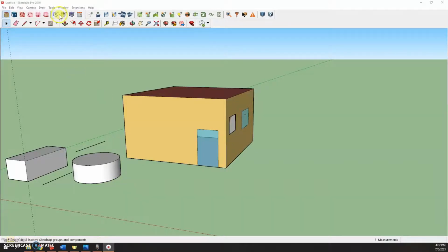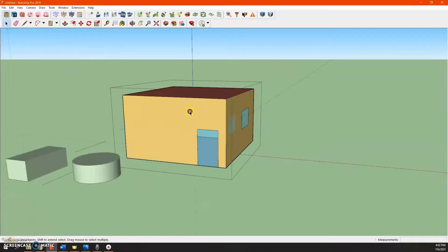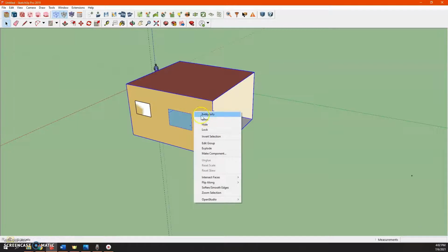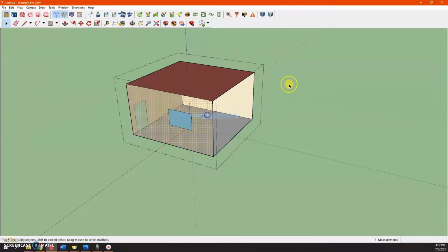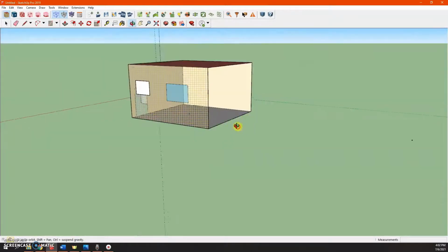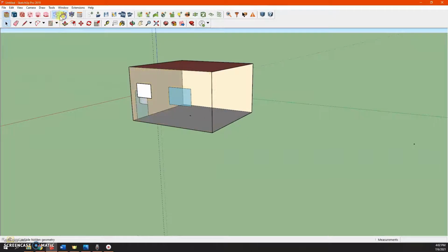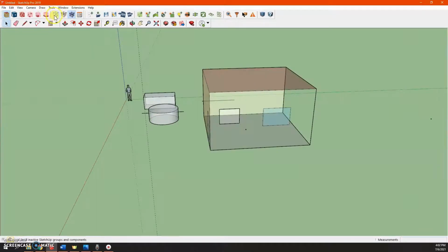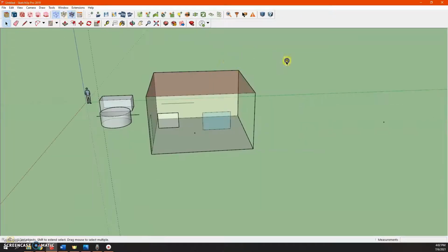And also I'll show you some of the view modes you can have. For example, hide rest of the model is when you're in a selected space and you click it, everything else disappears. So pretty self-explanatory there. For view hidden geometry, sometimes when working you want to hide certain walls just to make it easier to see some others. So here I hid that wall and you can see it as a grid as hidden geometry. And last but not least, this third one to the right makes everything transparent so you can see through walls and see through other fixtures.